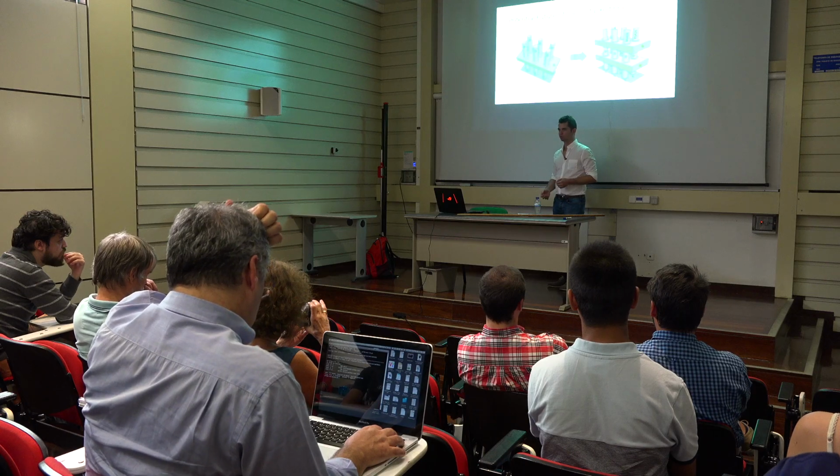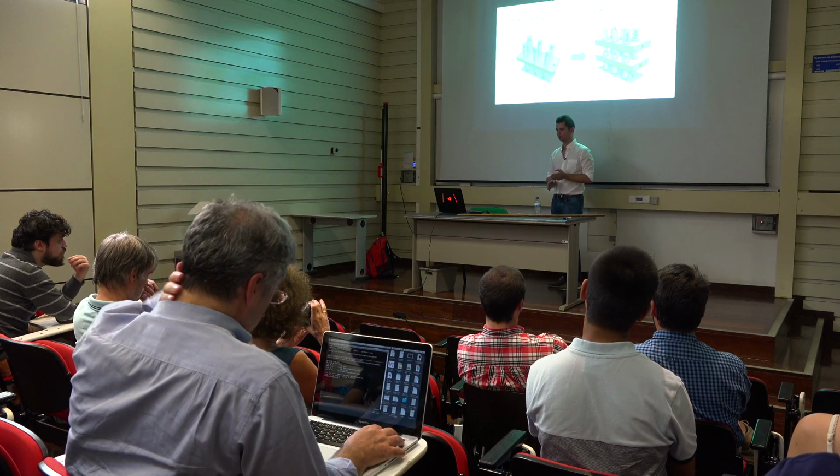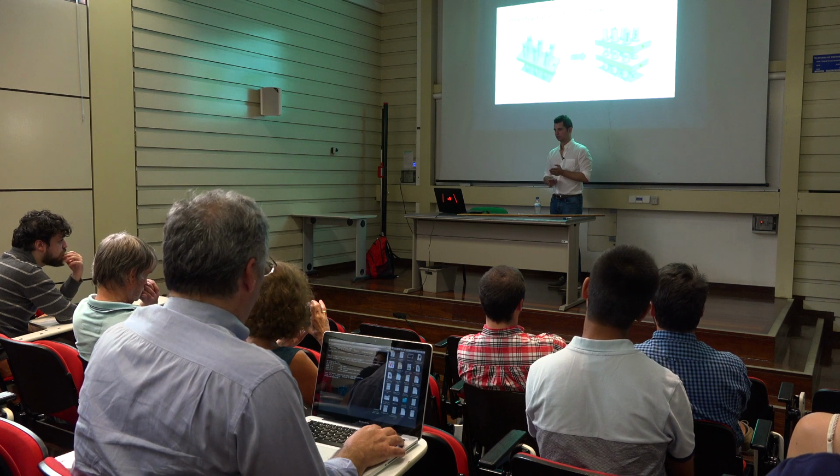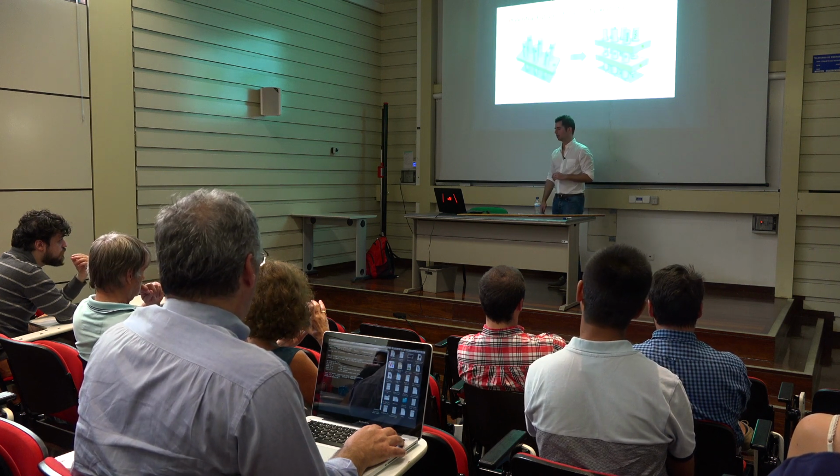Okay. Actually, layout and design, at least for advanced nodes, I would say come very hand in hand, because you also need to think about the way you're going to lay out in order to achieve the least amount of parasitic capacitances and the most balanced circuits. One rule of thumb is to do the layout as symmetric as possible.